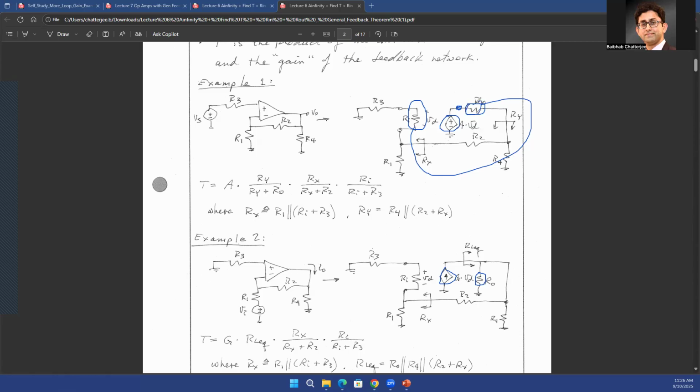So if you do that, in the first scenario, there was the series resistance and then there was something connected after that, right? And voltages get divided if there are two series resistances. So in the first example, you had the effect of R0 because it was a voltage division between two series resistors. One was R0 and the other one was RY. And RY is the complex resistance that you see looking down at this point, but let's just assume that everything was RY. So you had a voltage division between two series resistors.